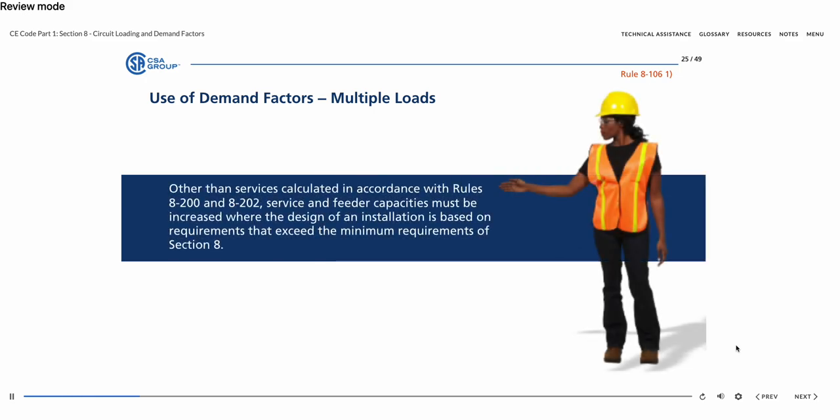Other than services calculated in accordance with Rules 8-200 and 8-202, service and feeder capacities must be increased where the design of an installation is based on requirements that exceed the minimum requirements of Section 8.